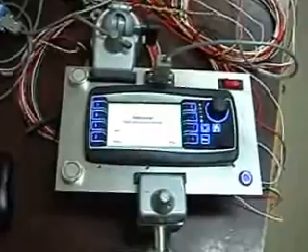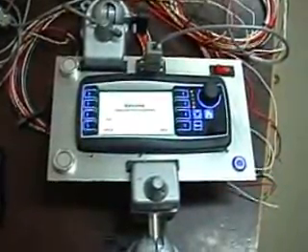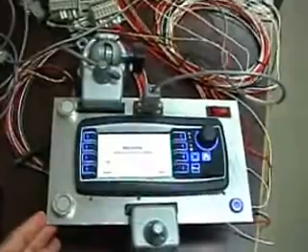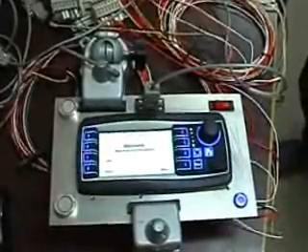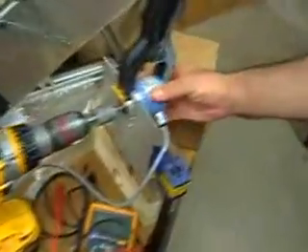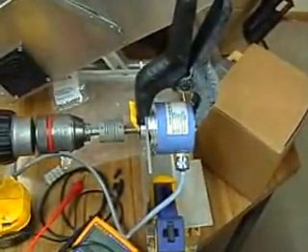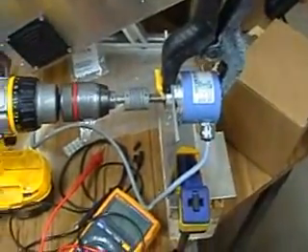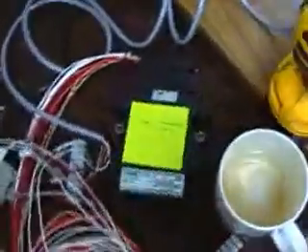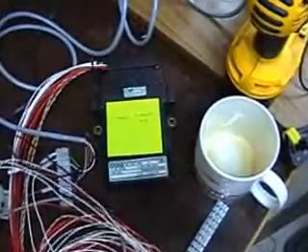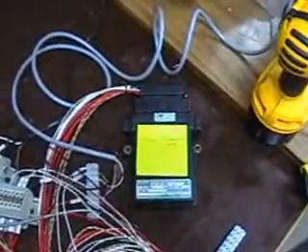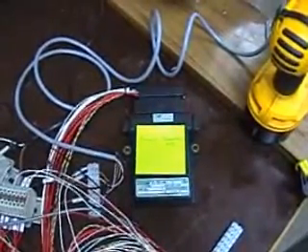So I think that should cover the lot. In this instance, we are supplying the control panel, which has this operator interface and the 2 switches and the D plus and the main on-off switch. You have the Wachendorff encoder, which is this one. That's been set up to be driven by a drill just for the sake of measurements and simulation of the test right now. And the ESX IOXp, which has got an AMP latched connector, with the latch being taken out so the connector can be taken out.